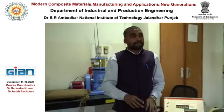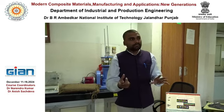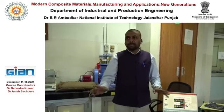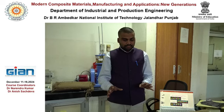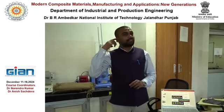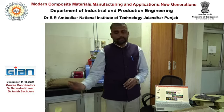So these are also kinds of defects. Yes, we should have uniform fiber volume fraction throughout the composite structure, but certain faults we cannot avoid, right? Certain things we can avoid, but we cannot avoid all the problems. There will be certain problems and we have to work with that, and we have to develop a composite with a desired factor of safety, so that that particular structure will work in real life. For example, your windmill blade, your automotive components, or the wing of the aeroplane.